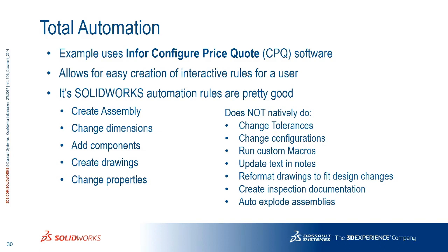But if I have a process that's going to be iterating through dimensions, iterating through features, it's a whole lot faster to write that in VBA, even though sometimes I don't like to use VBA. There just aren't as many tools there. It processes maybe sometimes 10 times faster than it would if it's an external program. And it's just because it's an in-process macro as opposed to an out-of-process program communicating back and forth with SolidWorks.